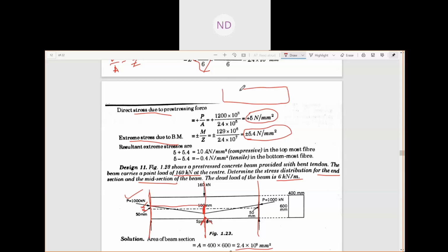in this way you had a beam, this is the center line, here you had your tendon, so you had an eccentricity here, and at that time your moment was what? Minus plus, right? Due to eccentricity your moment was in this way, tension at the top, at the bottom compression.